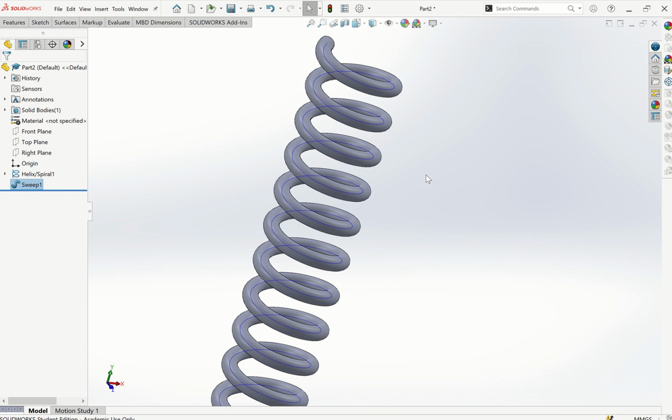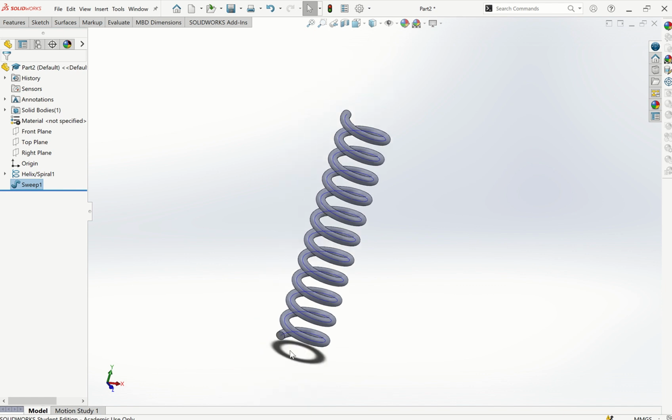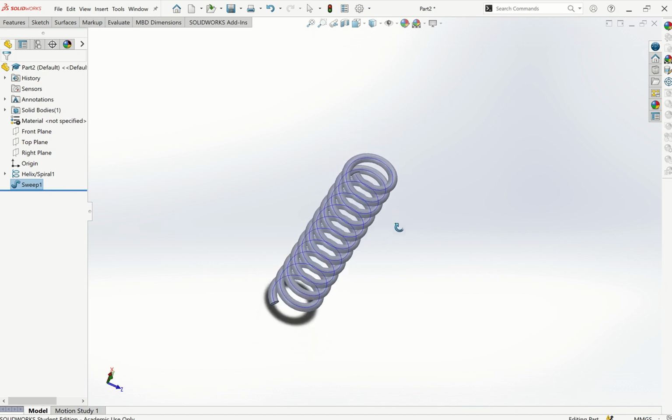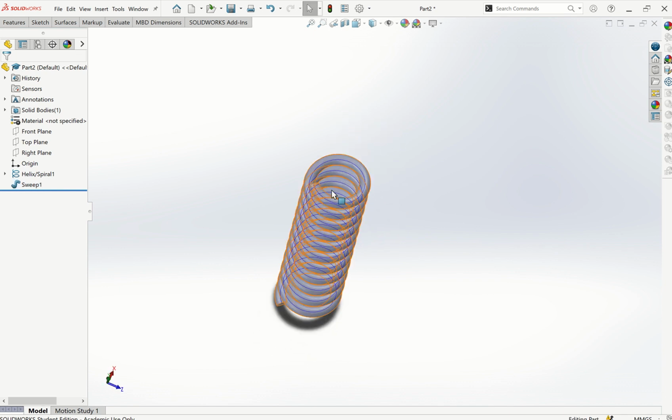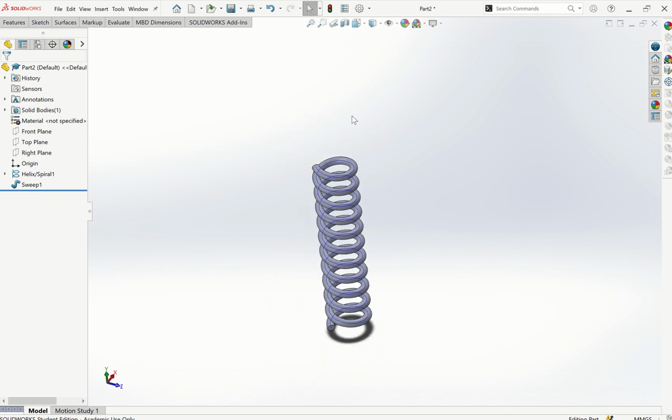That's finished. Now depending on what you want to put it on, if you're putting on a platform at the bottom, you might do a sketch rectangle and put it on that. Or some of these springs have hooks on the top of them, you can draw that in too. So I'll do the hook on the top here just to give you a demonstration of how to do it. So next up, I want a plane now that runs along that there, because the curved part at the top of the hook will come up from there and go across the top of the spring.